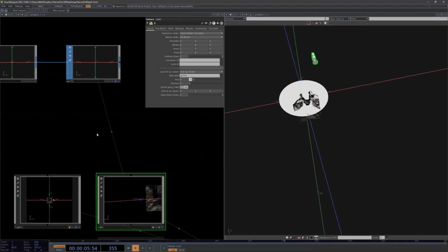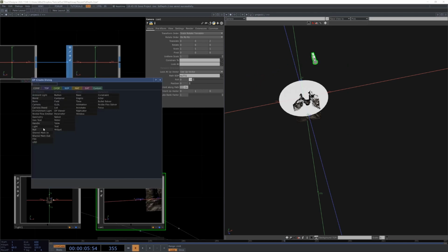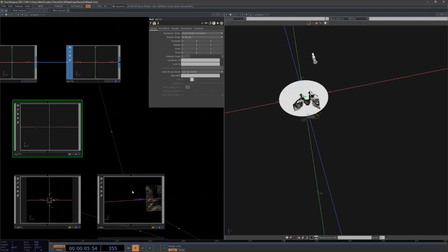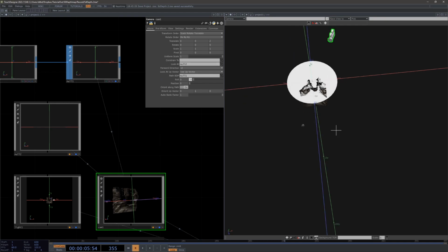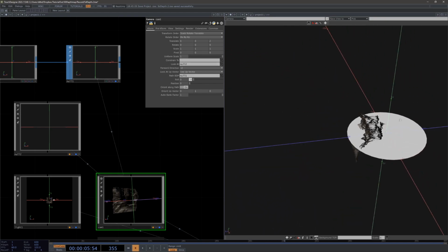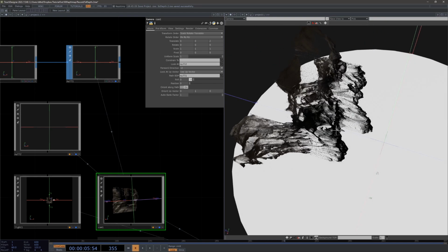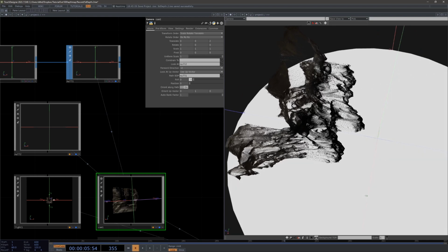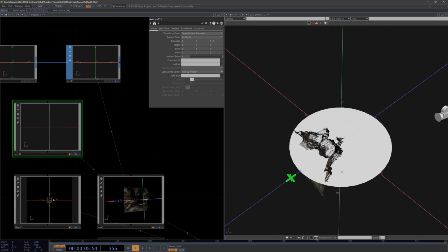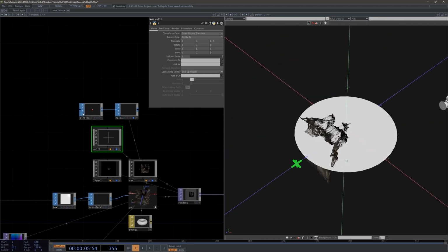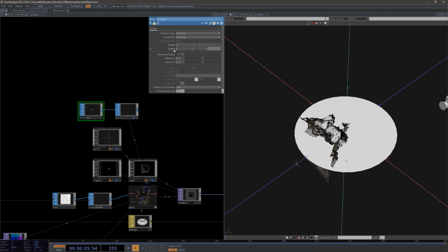So I'm going to add a null comp, and in cam1 I'm going to tell my camera to look at the null comp. The null comp is perfectly in the center, and maybe I want it to be outset somewhere, so the camera will really look at it. So I'm going to put it a bit further, even in 1.2, and I'm going to offset the circle as well to 1.2 in the z-axis.